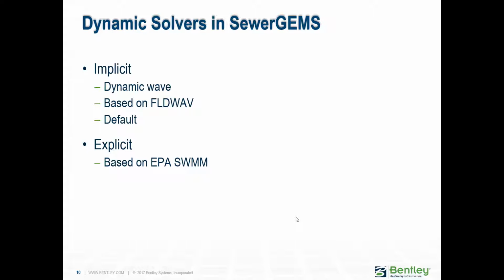Okay, so again, remember that this applies to the SewerGEMS users. In addition to the SewerCAD solver, SewerGEMS gives you two solution engines to solve the dynamic wave equations. The first one is the default, which is the Bentley dynamic wave solver. It's the one we called an implicit solver.